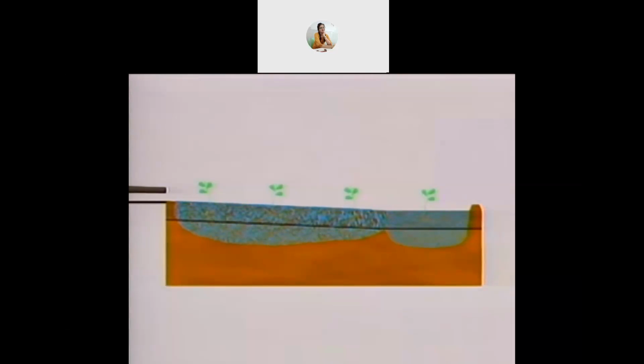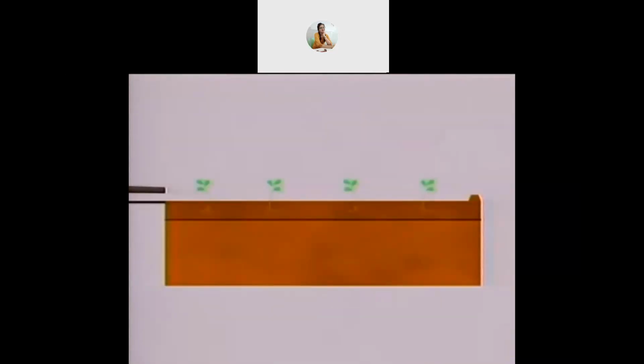Finally, we can level the whole field. If we do this, we need to apply the water at a much higher flow rate. Since the field is not sloping, we need more flow to get it down the field. Most level fields have shorter runs to solve this problem. As you can see, if a level field is irrigated properly, we get a very good uniformity, with very little deep percolation and no runoff.